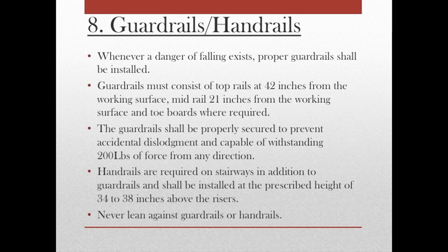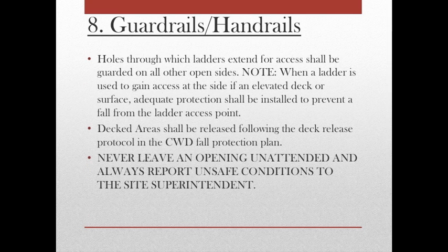Never lean against guardrails. Holes through which ladders extend for access shall be guarded on all other opening sides. Note, when a ladder is used to gain access at the side of an elevated deck or surface, adequate protection shall be installed to prevent a fall from the ladder access point. The decked areas shall be released following the deck release protocol in the CWD Fall Protection Program. Never leave an opening unattended and always report unsafe conditions to the site superintendent.